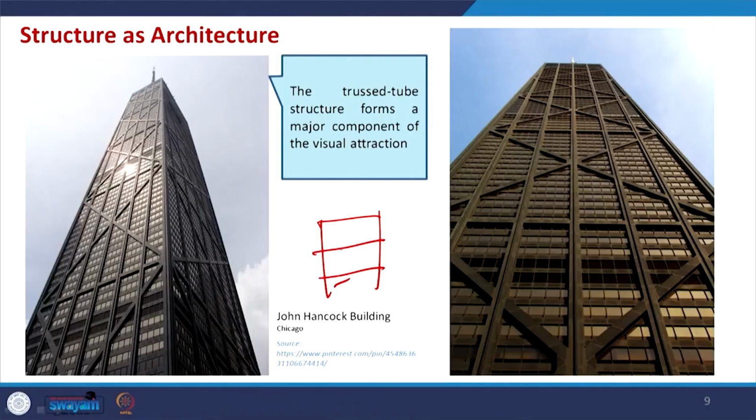For any building, it will have a self weight, so it is acting to the gravitation, but along with that there will be some lateral force, and when it is a high rise building the speed of wind will increase. So, lateral force as wind load will have some impact on that, and along with that the seismic one, when there will be a movement of the earth surface. That will also create some lateral pressure.